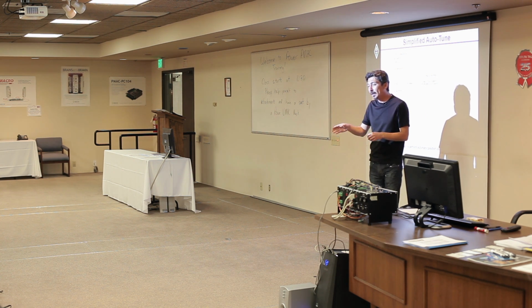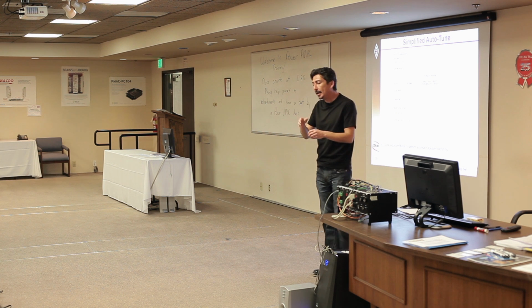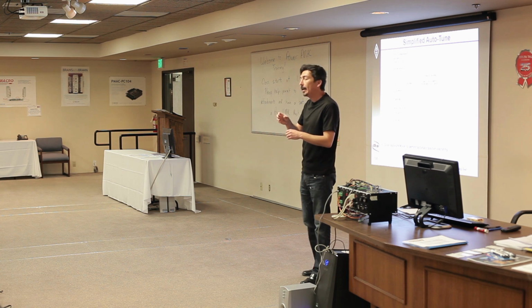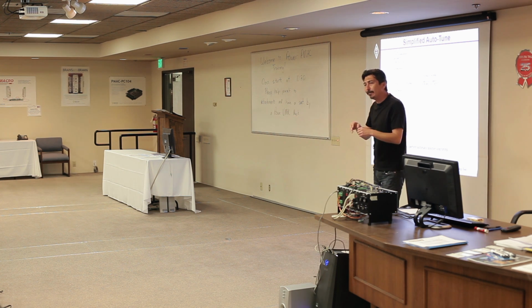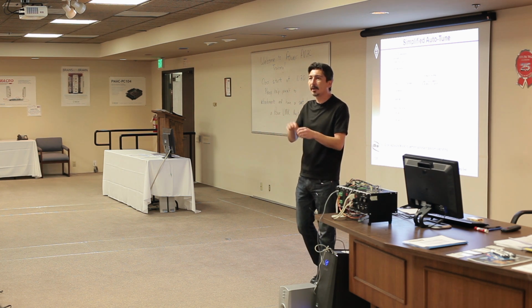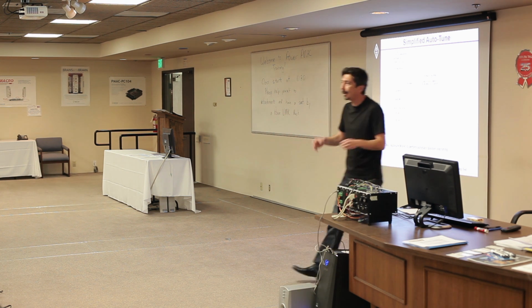The difference between this and the other is this is going to be an iterative style estimation algorithm. And it's going to do several auto-tune moves. And there's a stopping criteria. There's a logic behind it. And it's going to come up with the gains, everything for you, so you don't need to specify the damping ratio and all those things.